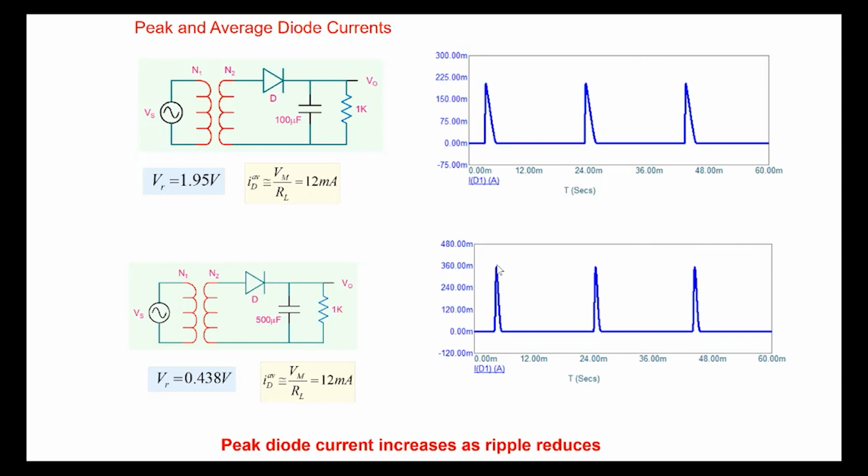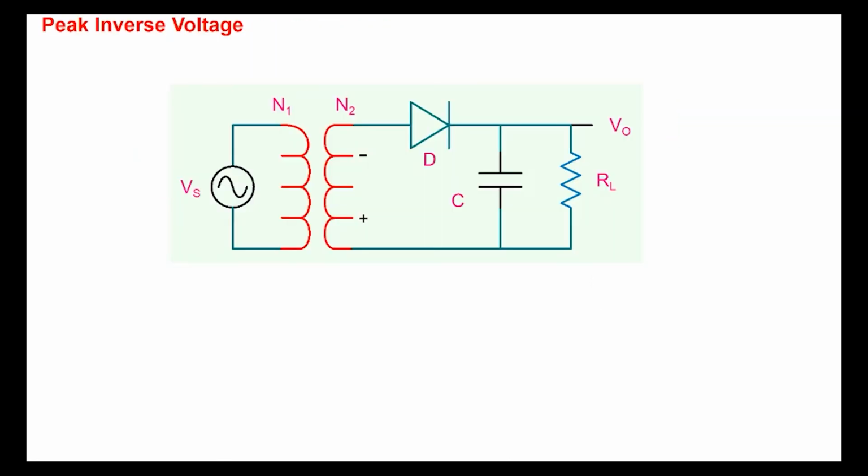And all right, so the other thing was peak inverse voltage. So the forward voltage is forward. When the diode is forward biased, there is a drop of, let's say, 0.7 or 0.8 volt or so. But we know that in the negative cycle, the diode is reverse biased. So let's say we have the input voltage here, and using the transformer turns ratio, we have generated a secondary of 12.7. So when it reaches the negative peak here, the value here will be minus 12.7.